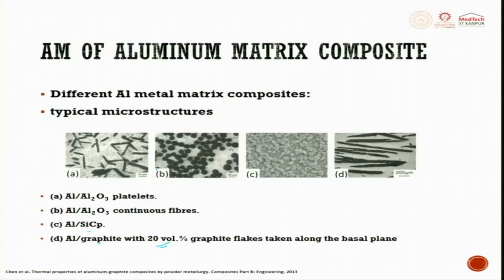So, aluminium finds a lot of applications in automobile, aerospace, entertainment industry and also biomedical applications. In terms of instrumentation, they find a lot of applications. Next is nickel: wherever it is high temperature and where they don't bother much about density, they go for nickel matrix composite.